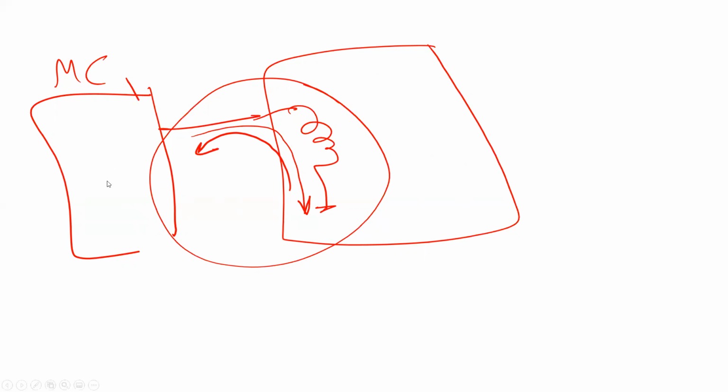So what can we do? Usually we put a diode this way. This is not microcontrollers, it's more electronics, but you need to learn it. The purpose of this diode is that when you turn off, the stored energy discharges through the diode instead of discharging into the microcontroller and damaging it. You can always see this in your capstone or anywhere. We always put the diode this way. You should understand this one.